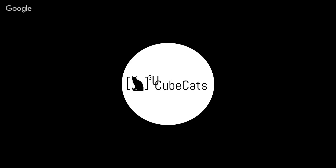But basically what you can do is establish a plane on the face of the soda can, attach an image to it, and then tell it to wrap that image around. It's a lot easier if you have a flat surface. So if this was a satellite and you wanted to put a little sponsor on it, what you can also do a lot of times, if you have text and an image, is stamp it in your CAD. It'll recognize the lettering and the enclosure as symbols, and then you can cut that into whatever it is you're doing.